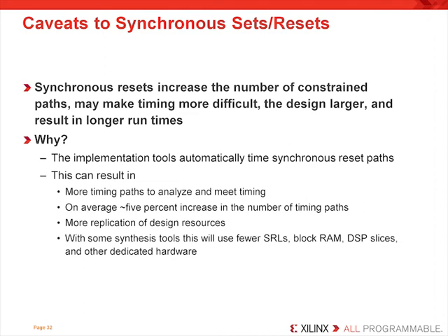Now, this is not wrong, since you want the design's timing analysis to be correct and help with timing verification. The impact is that the implementation tools will now have more paths to place and route to meet timing. This means more work to do and will slightly increase implementation times.